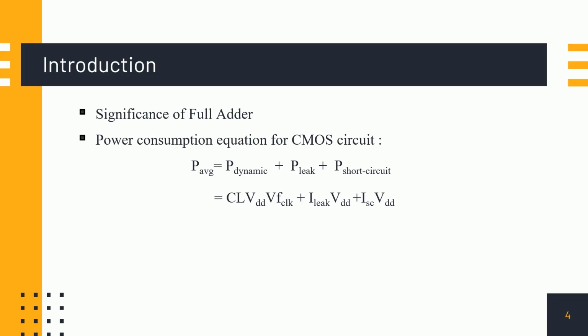At an early stage, VLSI design used complementary pass logic, which uses only NMOS to implement full adder cells. However, due to excessive power loss and transistor count, complementary pass logic was replaced by the static complementary technique that employed both PMOS and NMOS transistors. An adder which employs two or more logic styles is called a hybrid adder. Nowadays, researchers are focusing on hybrid adders to utilize the advantages of various logic styles for improving performance aspects.